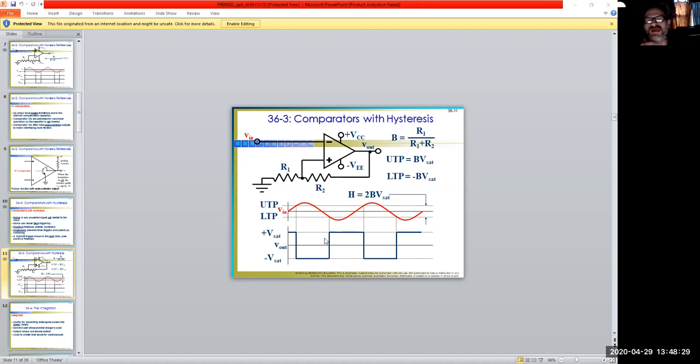We would have to do something further with this, because ideally a digital signal usually goes from a 0 reference point to a plus voltage, or, with negative logic, from 0 to the negative logic point. Here, because of the analog nature of it, we're going from plus VSAT to minus VSAT, so it swings DC-wise, ideally plus 15 and minus 15.